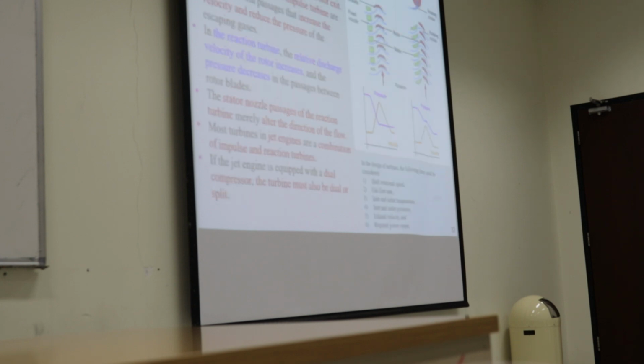The idea here, Shabab, is that the high pressure compressor should be driven by the high pressure turbine to spin at high speed. Then the low pressure compressor is driven by the low pressure turbine, along with the fan, spinning at lower speed. In some situations, we have to have a gear to reduce the shaft speed from the low pressure turbine to drive the fan, because the fan has to be driven at even lower speed to draw more air and consume less power. Please go ahead.